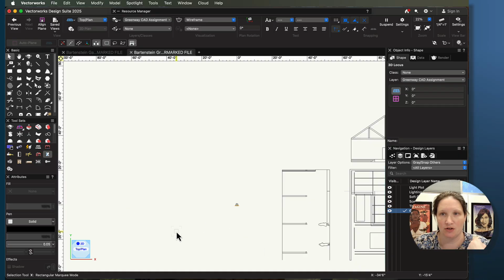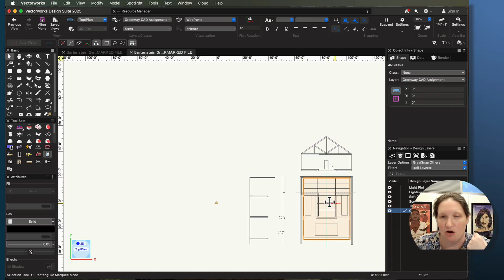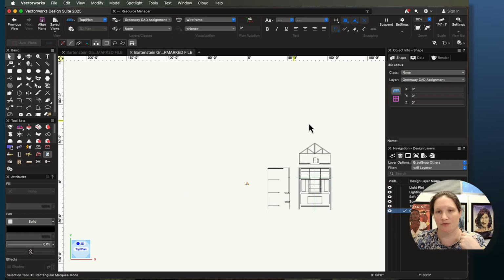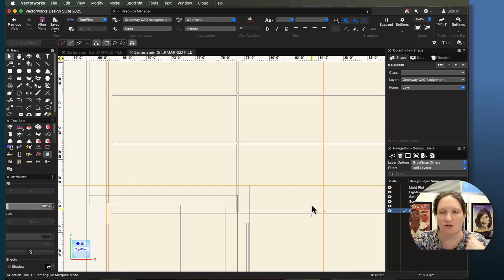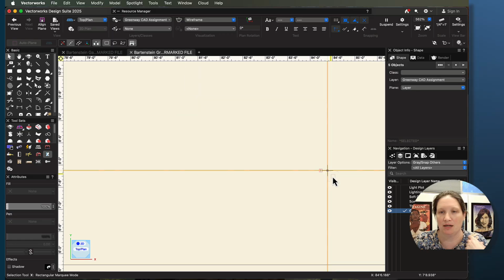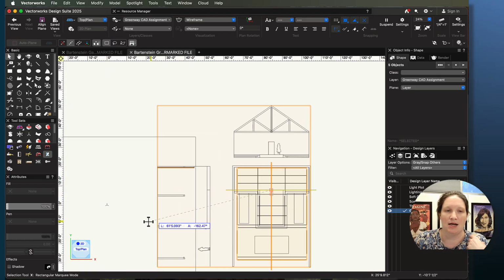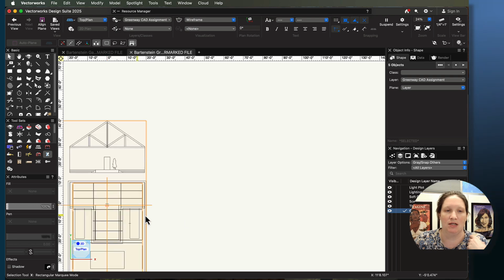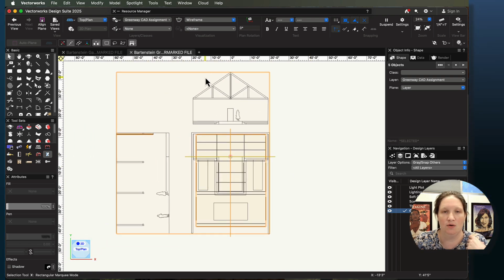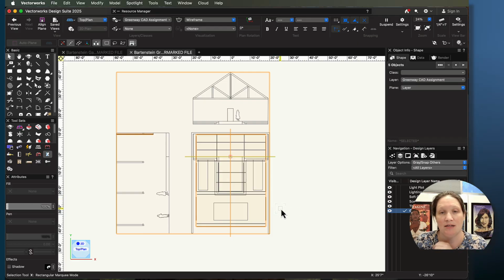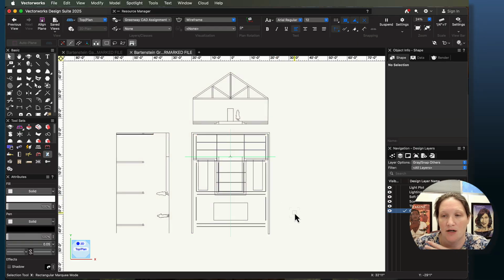Center of this drawing. And I will now pick up all of this stuff over here, right? I will select it all, pick it up by the intersection of my center line and plaster line. So it'll be like object, object, and then I'll zoom out and I'll slide that over and I'll line it up with my 3D locus. So now I know that my whole theater is centered on that line, which is where I would like it to be. So that's a great place to start.